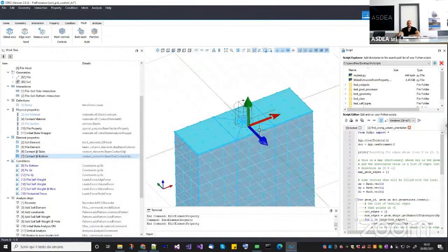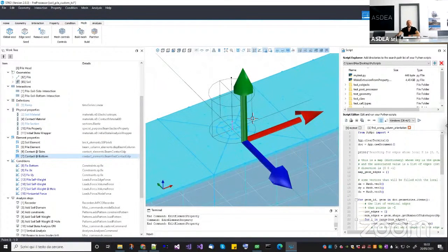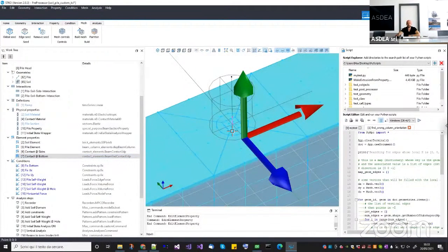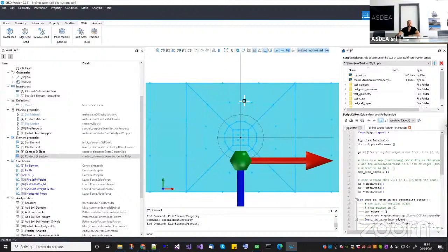And as you can see, the cylindrical local axis is actually pointing, well, here it's pointing in the y direction, but when projected onto the beam, the necessary thing is that the z direction is coming outside, because then it takes the x direction from the direction of the node. So the only important thing is that the z is going outside, and the cylindrical one is the only one that guarantees that the z local axis will go outward. So let me zoom here, and let me hide this one.